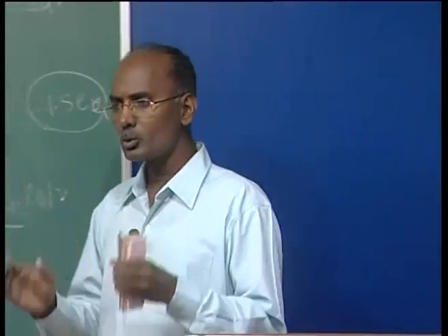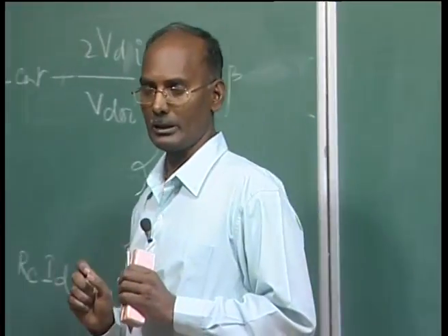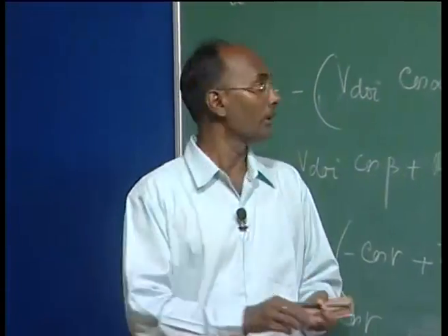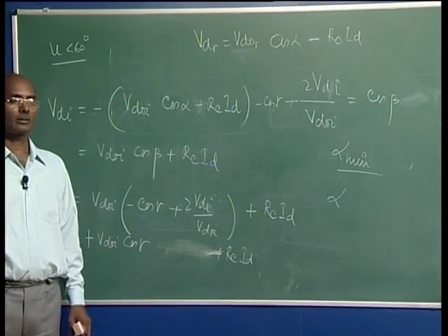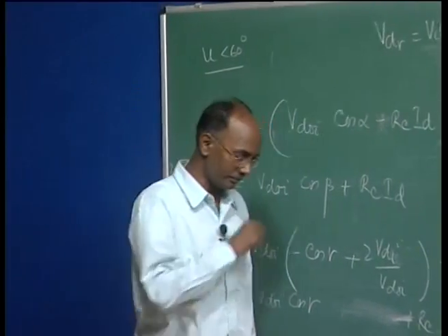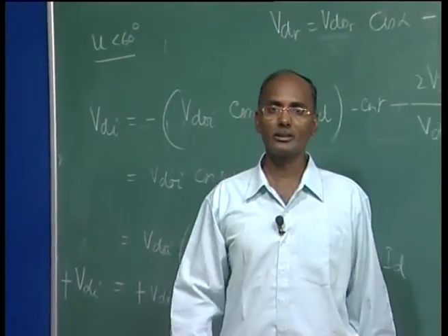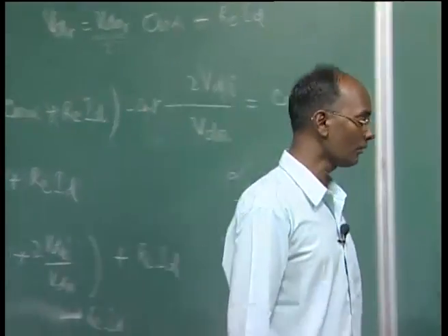So, this 2-3 valve operation is actually the normal operation of HVDC, of any converter circuit, I can say. Normally, your U is less than 60 degrees, but there are some abnormal conditions where we can exceed 60 degrees. We will see here.